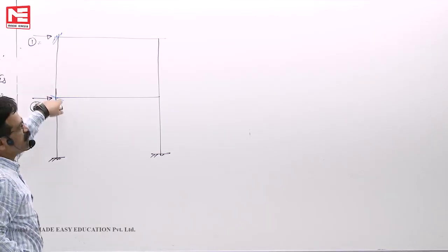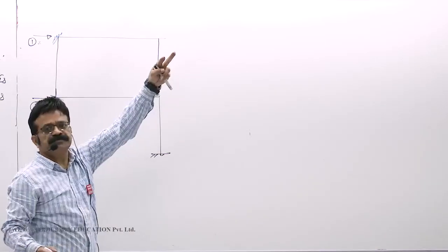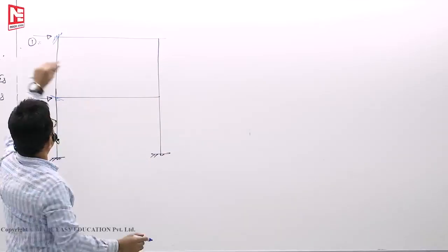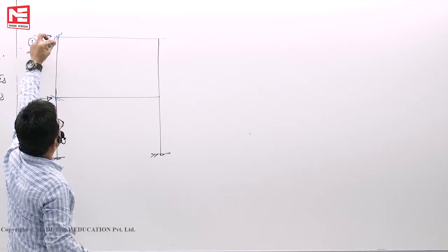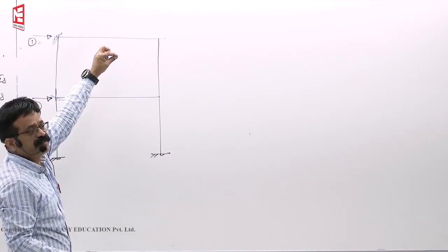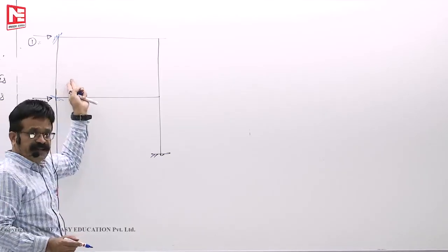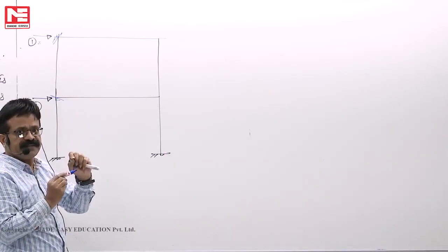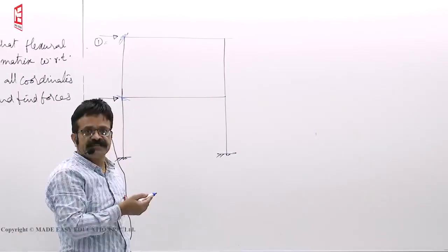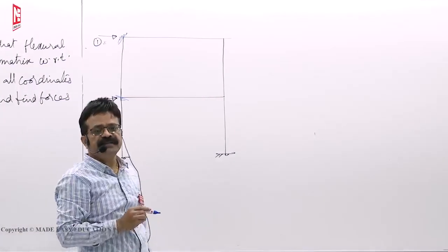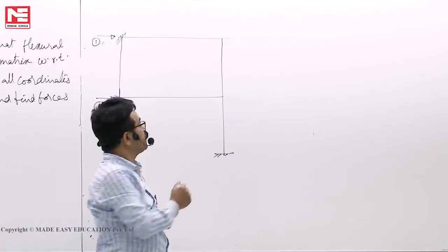This is called the symbolic representation of fixing the coordinates. If I fix it, this cannot move. This also cannot move. Now, after fixing this and this, hold it, apply unit displacement. But for rotations, there are no coordinates given. Still they cannot rotate because of EI value infinity. Because EI is infinity, they don't rotate, otherwise they will rotate. And that rotated deflection curve means you will get a very complicated matrix.